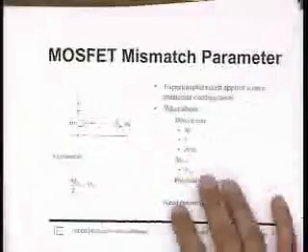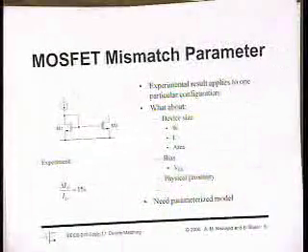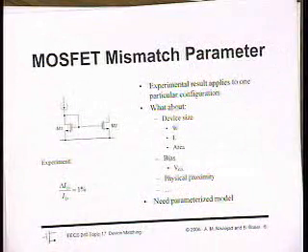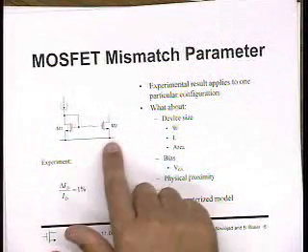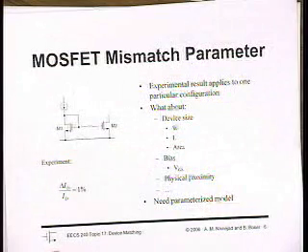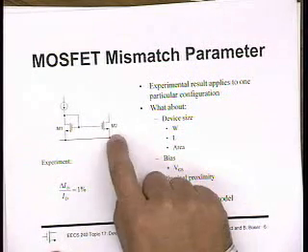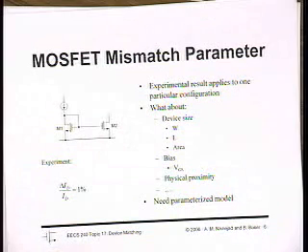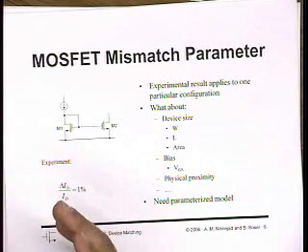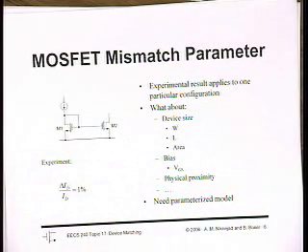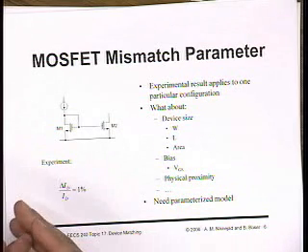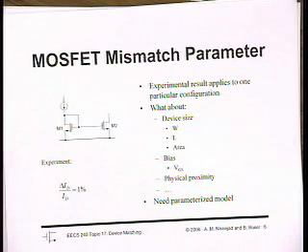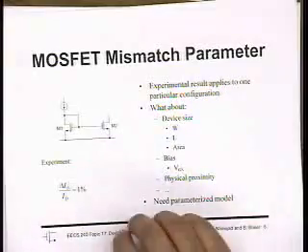And we've already looked at mismatch, but we only looked at it in terms of, let's say, for instance, we analyzed the current mirror and we said, well, how much is the current different between these devices, given that there's a threshold mismatch, given that there's a beta mismatch between the transistors, and so on and so forth. But we had no idea how to control the mismatch, right? The beta mismatch was a given, the threshold mismatch was a given. What we'd like to know is, how do those things vary with the layout of the device? And Pelgrom's model is exactly that.